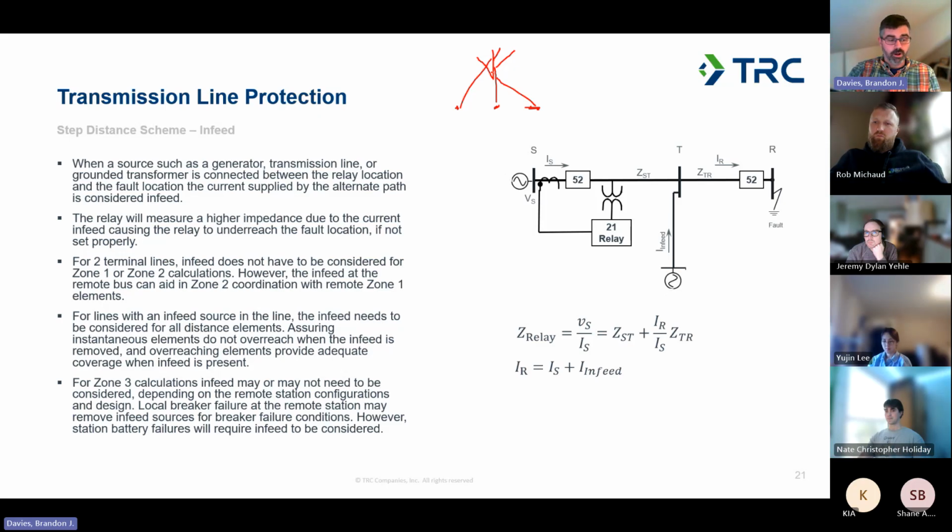You get three conductors that all have roughly the same current going through them for a multi-phase fault, and it kind of balances out because they're all balanced. When you have two lines, it might be that one is sending fault current in one direction, the other one's supplying fault current in the other direction, or a different magnitude. That's really where the mutual coupling consideration comes in, when you have two different lines that are seeing different electrical parameters, physically close enough that you have that mutual coupling effect.